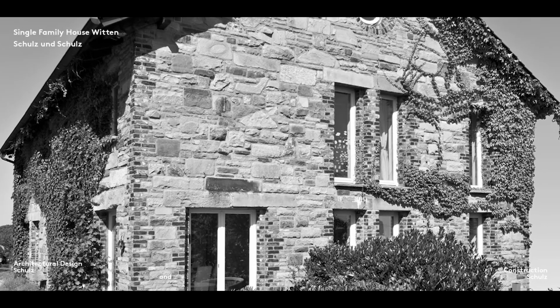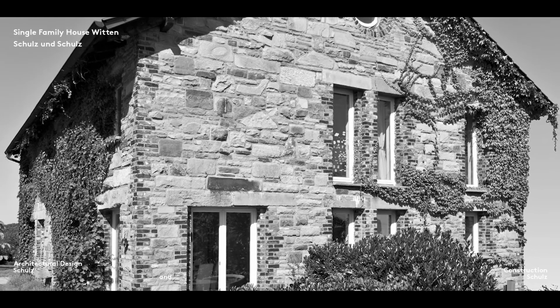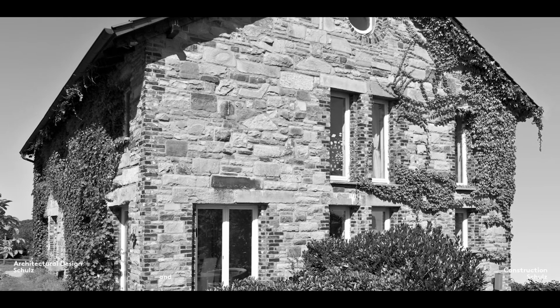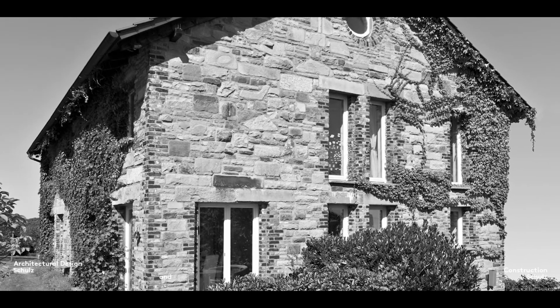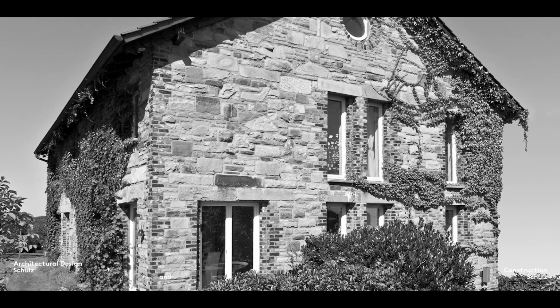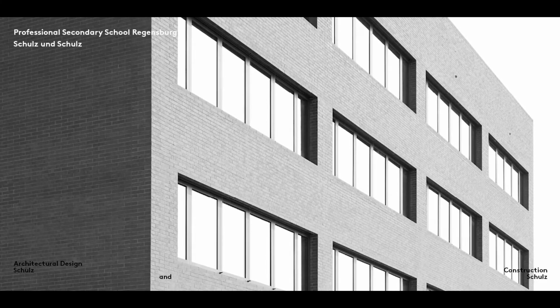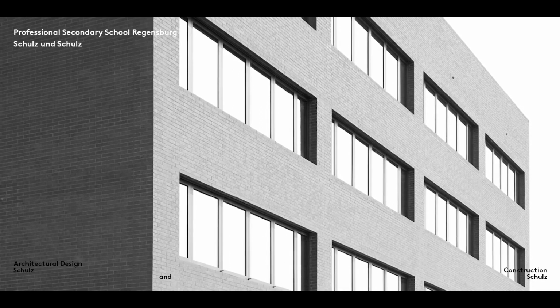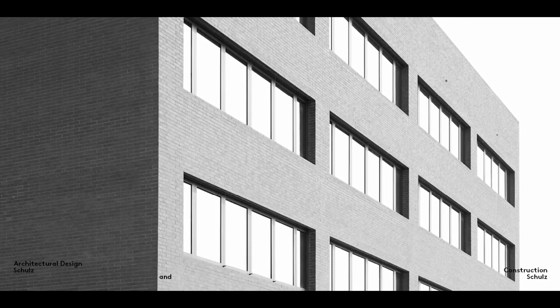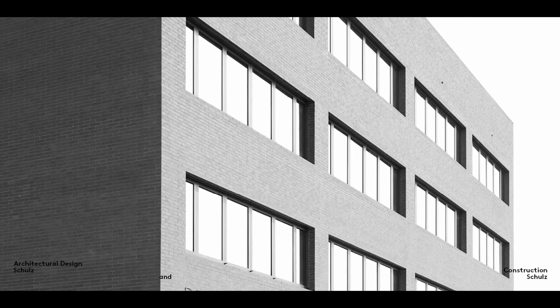If you want to create an irregular masonry effect, you will have to use natural stone because prefabricated bricks and blocks always come with identical dimensions. Natural stone is not subject to the rules of modular coordination. In regular brick and block work, on the other hand, modular coordination does apply, dictated by the brick or block size. All length and height measurements, including wall length, column widths, and windows, are multiples of a half brick length or a full brick height.